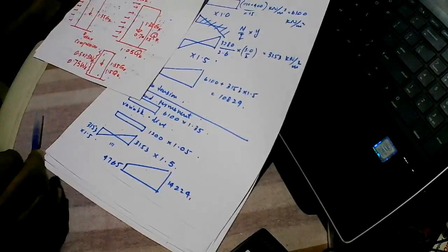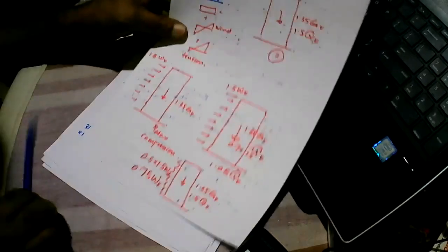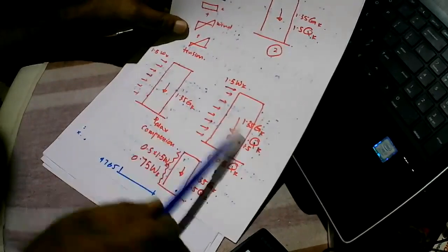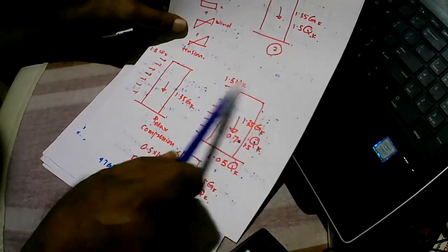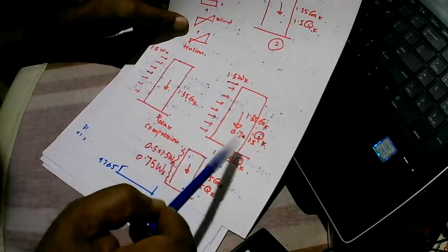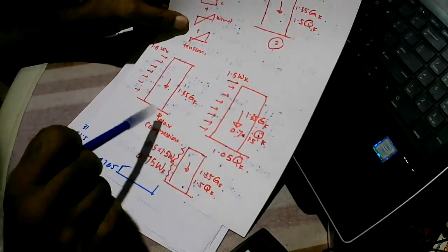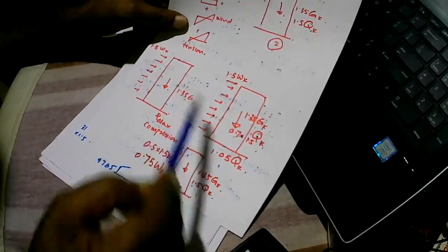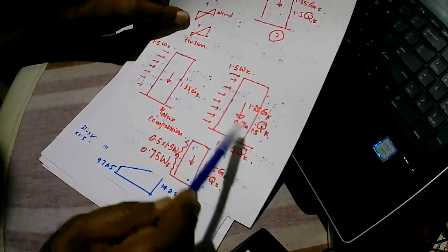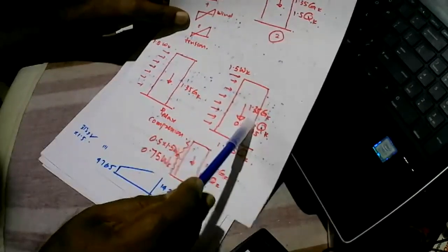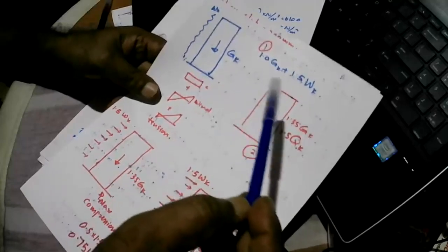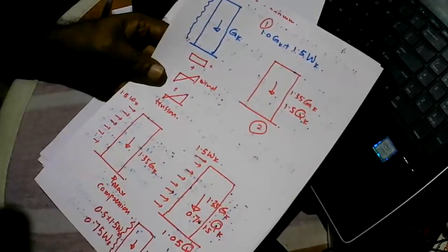And you can see all the other cases will be in between. So I will not consider those cases. When you compare these two, you can see this will be more critical than this one because we have an additional vertical load acting on this one. Whereas because the wind load is dominating, this will be more critical than this one. So I have considered this for compression, I have considered this for tension, and I have not considered other ones.